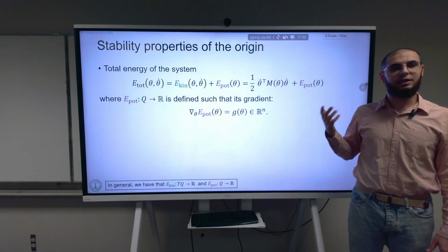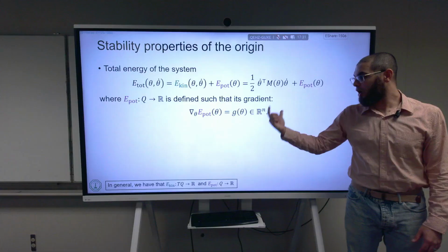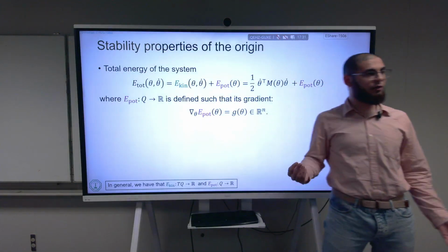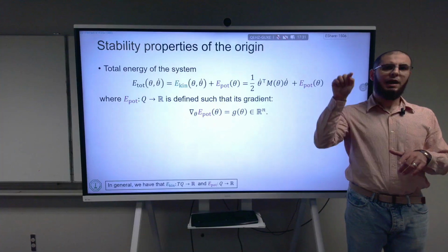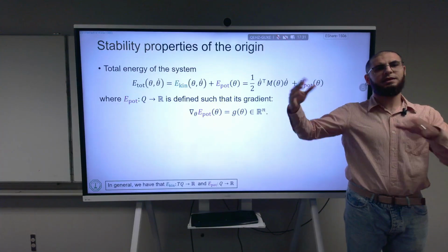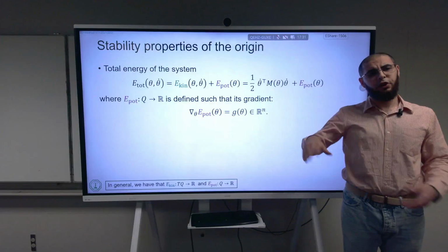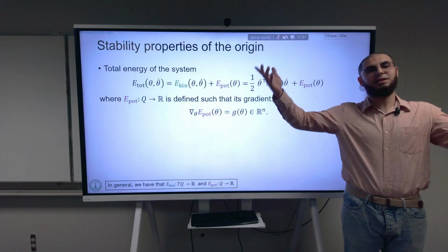And the potential energy, we never talked about it, okay? And we never mentioned actually that the gravity torques are given by the gradient of some potential energy with respect to theta. We never derived the gravity torques like that. If you remember, we looked at, for example, having the gravity as an external wrench at every link at the center of mass, and then we combined all of that into some torques that we call the G. And another way to talk about gravity, we said we can think of the inertial frame itself as accelerating.